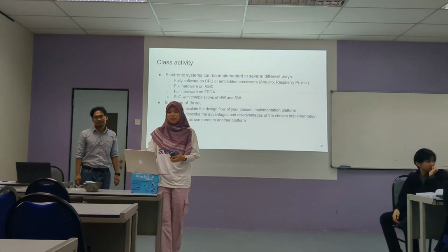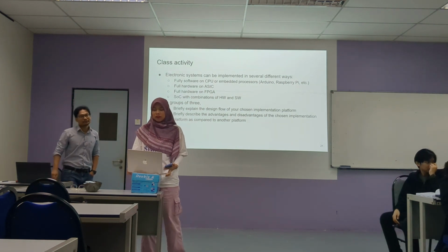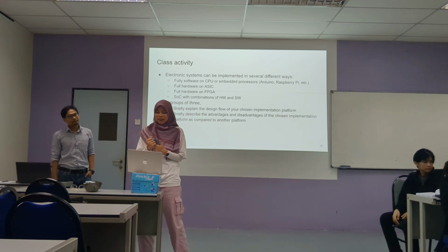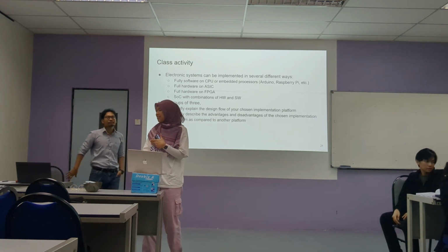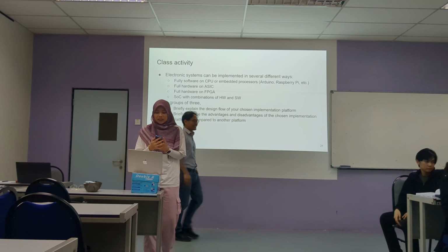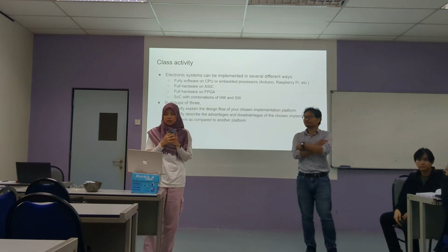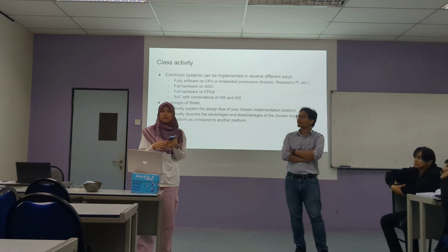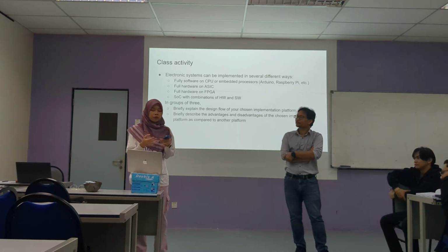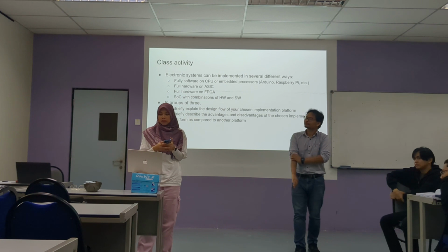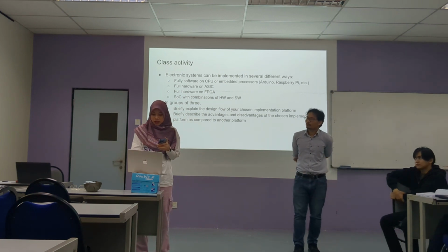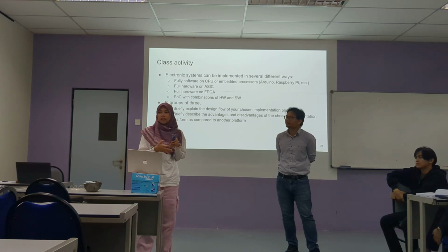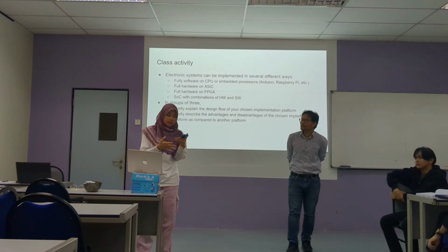Hi everyone. So I'm from group 2. Our comparison is FPGA vs ASIC, starting with the design flow implementation. It starts with the specifications, which means that we need to define the functionality and the requirements of our system. Next is the high-level design, which involves HDL, like Verilog or VHDL.